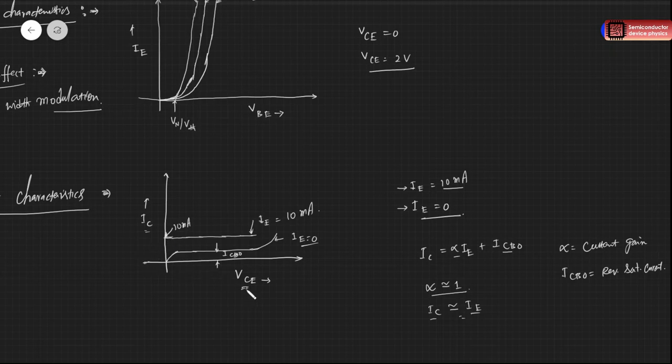And if you go reverse, if you change the polarity of VCE, or apply negative VCB, then the junction will also be forward biased. So in that case, this region goes to the saturation region. And I'm not drawing the cutoff region beyond this line. Every transistor has what is called a breakdown voltage, not cutoff, breakdown voltage. So I'm not drawing beyond this breakdown voltage.